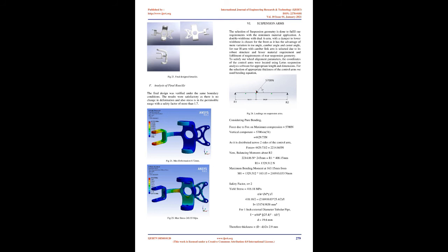B. Capture curvature. To capture small curves and to have good quality mesh at curvature. The minimum curvature size taken was 0.5 mm. C. Capture proximity. This is the most important feature. It captures all proximities and helps to generate a small and good quality mesh in these areas. The minimum proximity size taken was 0.5 mm.